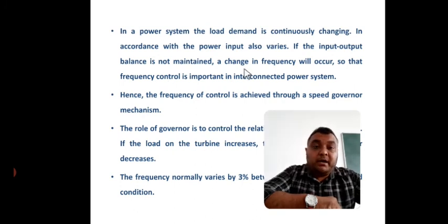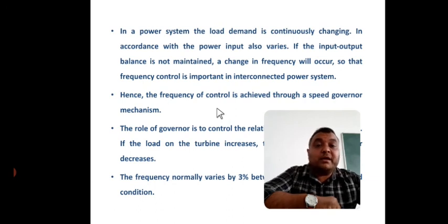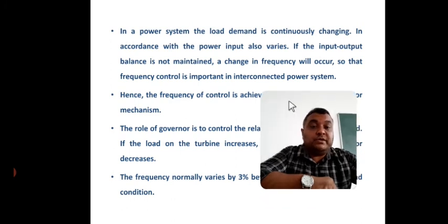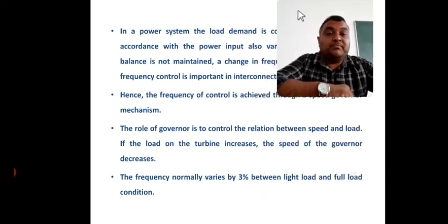The power input also varies accordingly. If the input-output balance is not maintained, a change in frequency will occur, so frequency control is important in an interconnected power system.